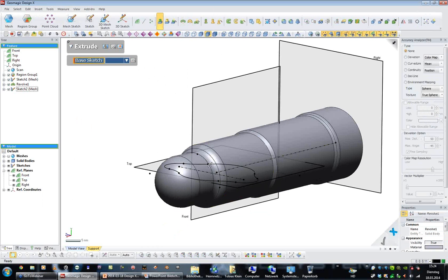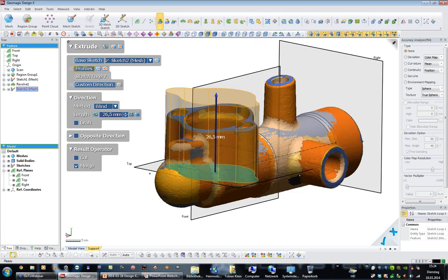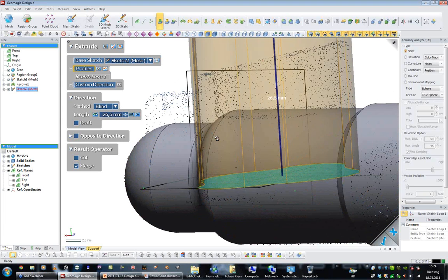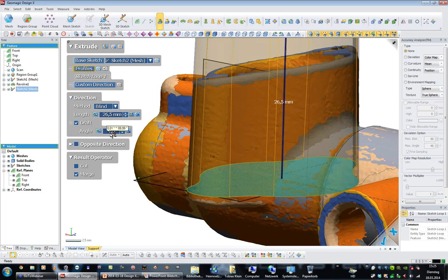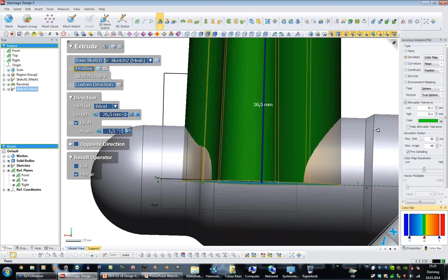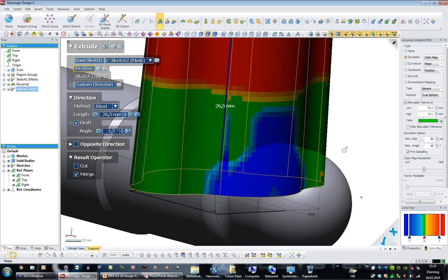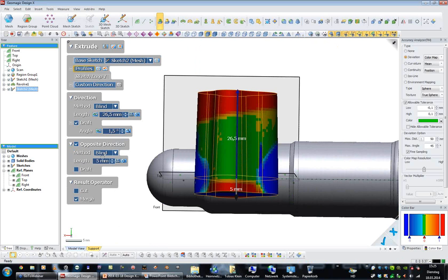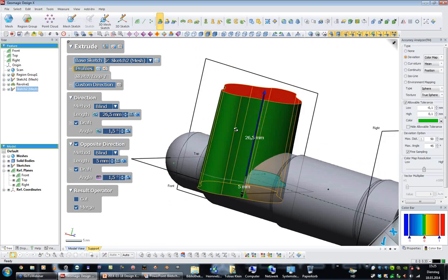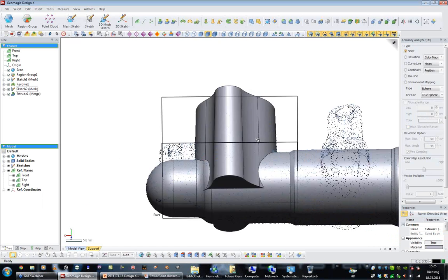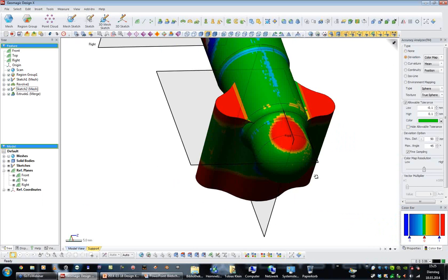Now we can extrude this 2D sketch to cover this shape. And before we checked a 1.5 degree draft, so now we can enter this draft here as well, and check if our assumption was correct, if everything is inside the green tolerance area. And we can also extrude to the other side. We have the same draft here, but in this direction. Okay, and it will be merged with the other part. So now let's see the whole deviation of the part.